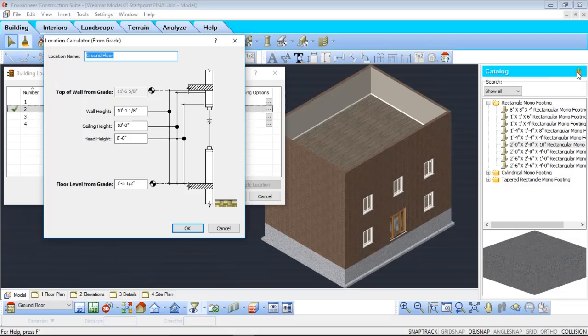So we got another one here. If I have a crawl space with concrete walls and footings, and the crawl space slab is 3 feet below the first floor level, would the 3 feet be a -3 foot or +3 foot designation? So it would be a -3 foot designation.